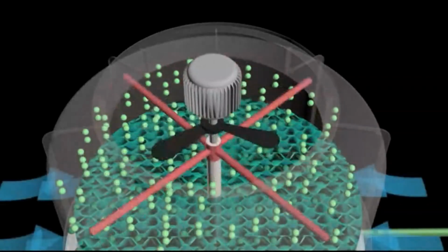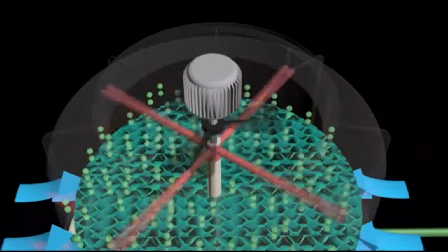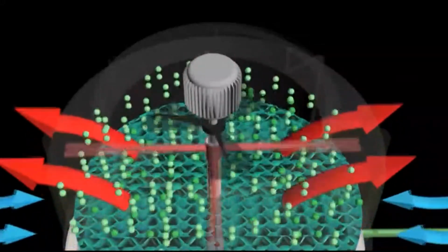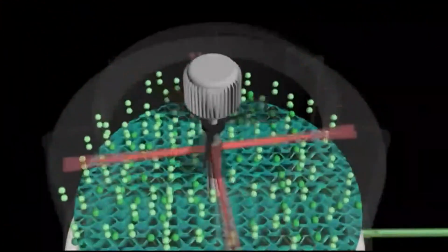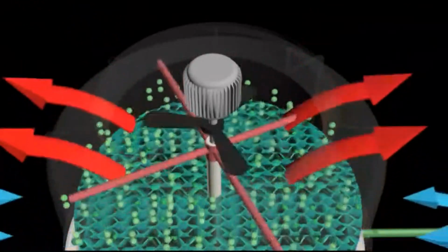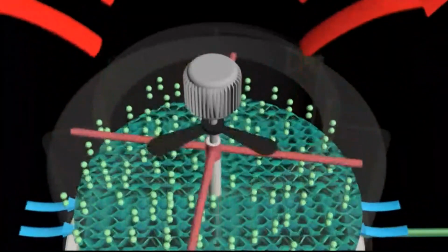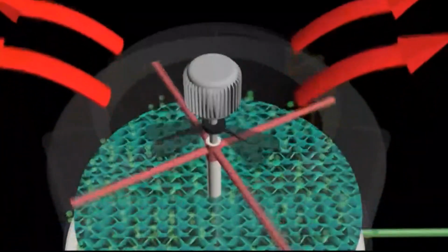Water will gush down through the fins to reduce the speed of water going down. This can delay the time so that the heat can be absorbed more effectively by the surrounding air passing through the fins. Air through the fins is forced by a rotating fan on the sprinkler blade, rotated by the motor. This fan rotates with its gusts upward.